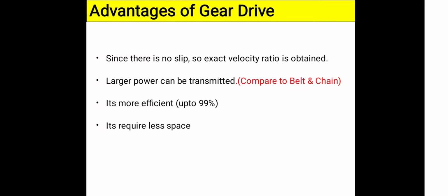Next, the non-parallel and non-intersecting axis gears. The other name for them is skew axis gears. Under this classification there are hypoid gears, worm and worm wheel, and spiral gears. These gears are used to get a great speed reduction ratio between the input and output shaft. Other gear mechanisms can also reduce the speed ratio, but comparatively the worm and worm wheel is used for more speed reduction.